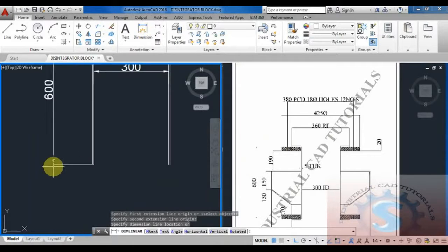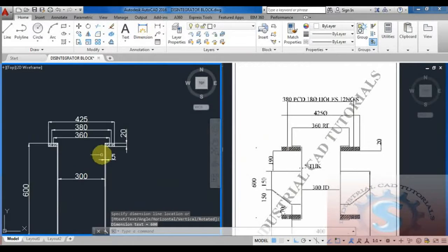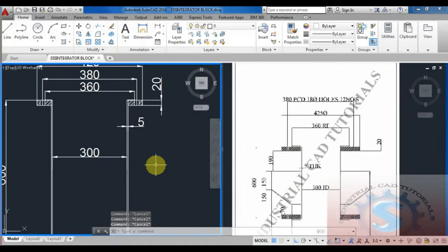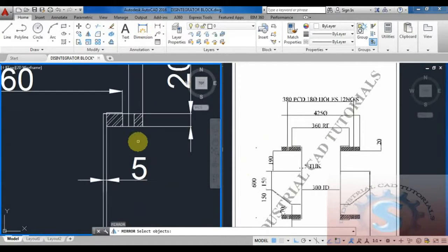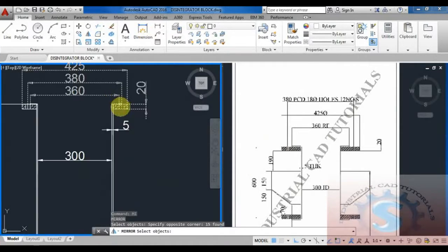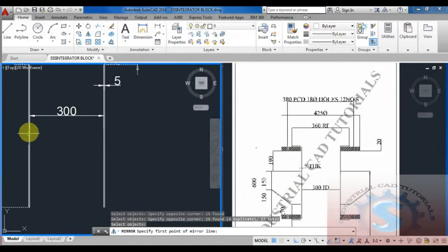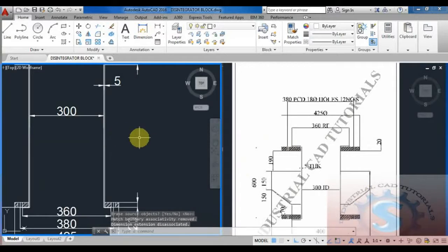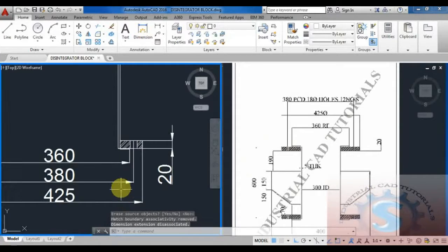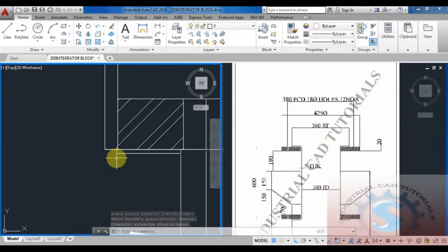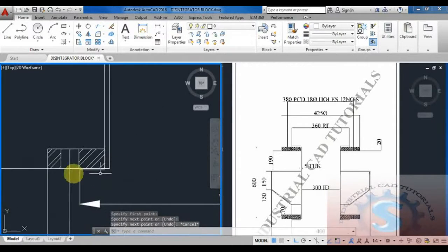See, this is the 600 height I'm showing. All the dimensions are correct. Then you want to develop the 600 dimension on the other side by using the mirror command. Simply select the reference of the two endpoints of the horizontal place. You can develop this like this. By using the mirror command, it is very simple to construct the drawing, and the drawing is completed.